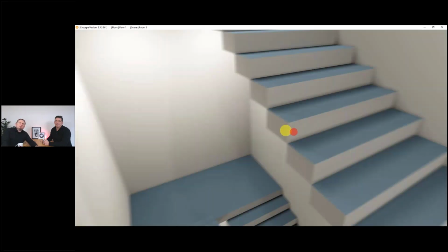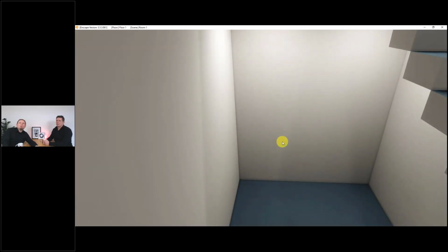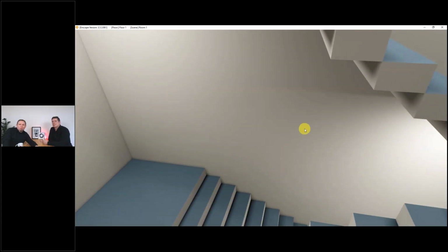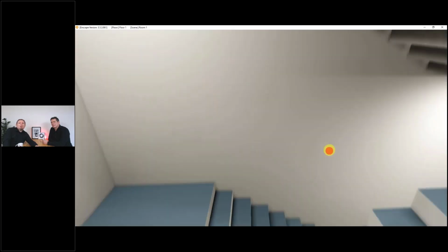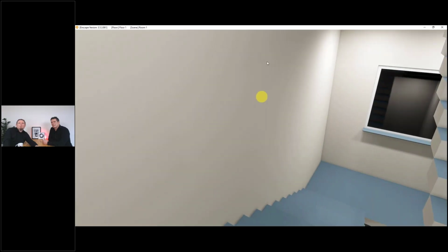And here it might be useful to think, okay, if I need to place more luminaires than these ones, maybe I need to place luminaires on the wall, which is quite common in staircases, that you use the wall as a location for luminaires. And here you can imagine, okay, I'm walking down and up, and it would be okay to have a luminaire here, but maybe at a certain height up to 2 meters, so that you are not glared or directly impacted by the luminaire.